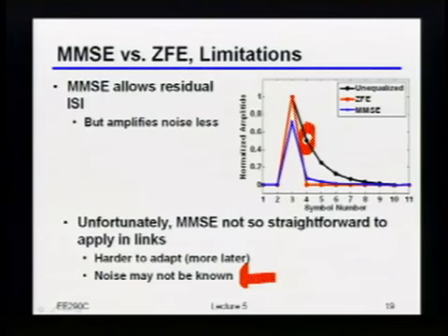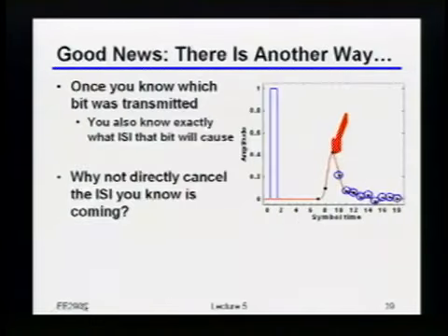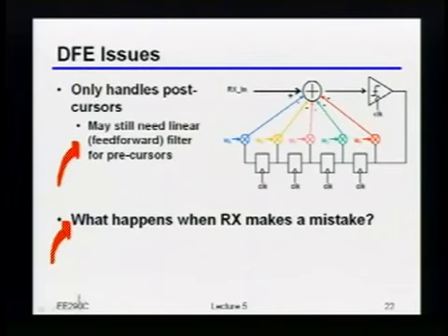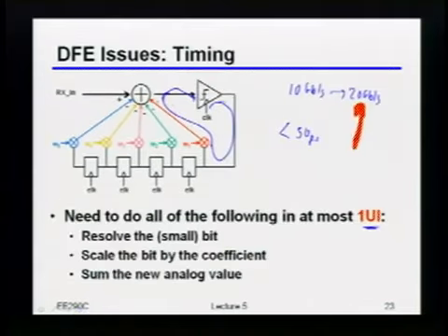Yeah. So to do DFE, basically we don't want the noise amplification, right? Right. So the fundamental difference between DFE and a linear equalizer is only that you don't have noise amplification. But what I mean is, if you have this feedback, you basically have added noise and the input at the same time. You're just saying that, hey, fundamentally these are devices, and those devices have noise. So yes, that's right. But how does it scale? I think it's maybe a square root relationship depending on the number of taps.